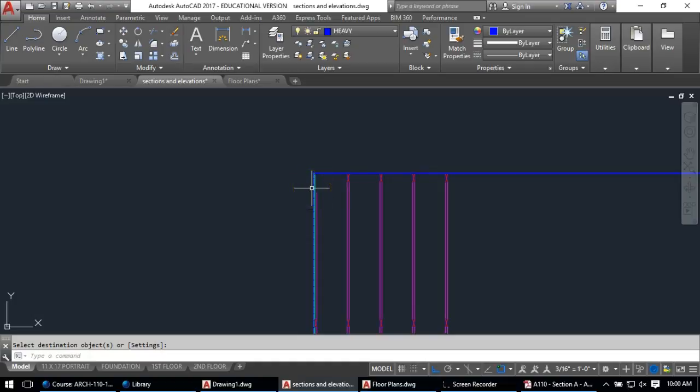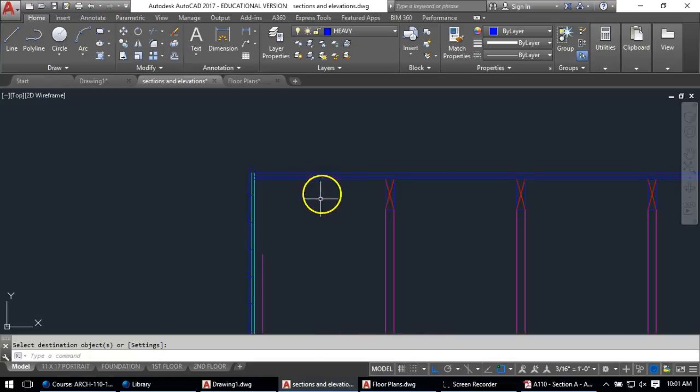And let's see, let's go and take a look at my drawing here. Let's see, I'm going to look at some of these notes. I'm looking at the big section here, to some of the detailed notes. I had a 2x6 fascia there. It's 27. It's a 1x10 finished fascia. Okay, that's what I was looking for. So we got it. And a 29. 29 is 2x4. That's what I figured it was, but just wanted to make sure.